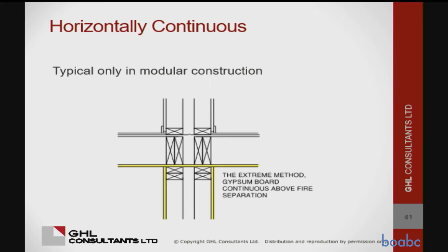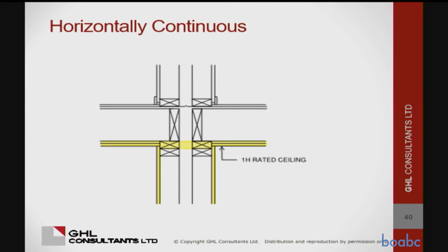The other question that comes up all the time, if you go back, is, oh my God, those top plates can't interrupt now, you have a hole in the horizontal fire separation that's made by the wall. It's like, well, the fire blocking, your double top plate at the top of the wall, is closing the hole in that wall, the same way that, or in the floor, the same way that the vertical fire blocking closed the hole in the other direction.